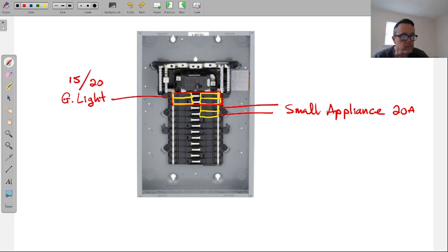If you didn't upgrade and you just added it and it went over average, would you start melting like the main breaker? So you wouldn't, you would just trip the main breaker. Okay. Yeah, and main breakers, tripping 150 amps is not fun. You're putting a lot of stress on that panel. That's a lot of amperage to be playing around with, having a breaker trip and then resetting it and having it trip again, because that's what's going to occur.